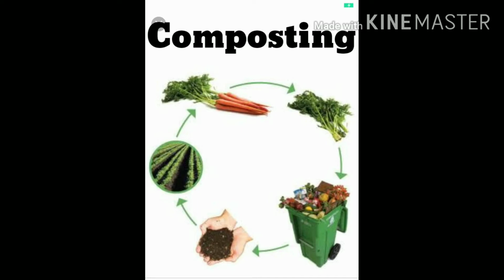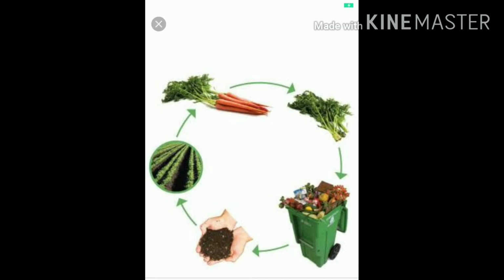Composting is a waste disposal technique where the biodegradable waste is decomposed by microbes and the waste is converted into manure or fertilizer. Heaps of leaves, grass, sewage, sludge, food waste and biodegradable house waste converts into compost, which forms topsoil capable of giving good crops. Compost is produced by the action of microbes on the organic matter. Microbes degrade carbonic material into simpler substances in moist, warm and aerobic environment.